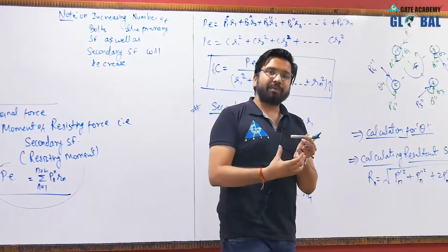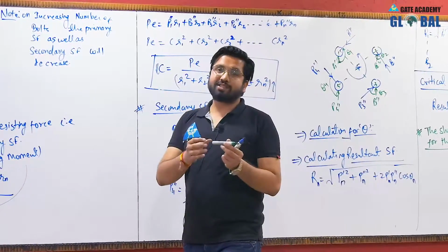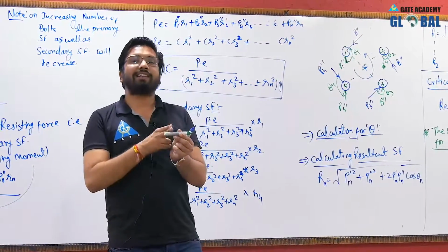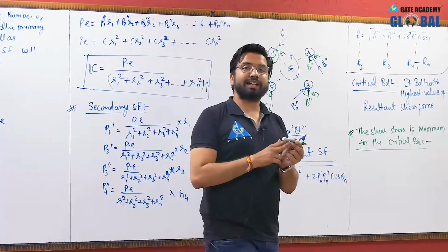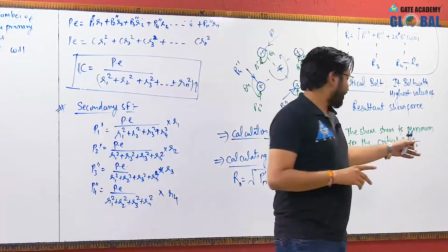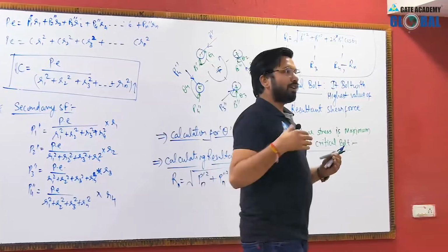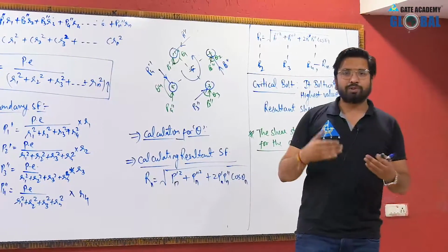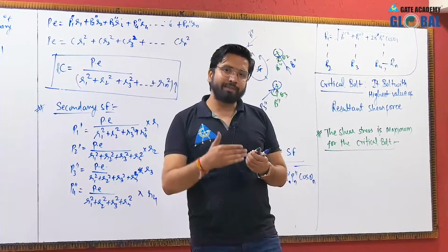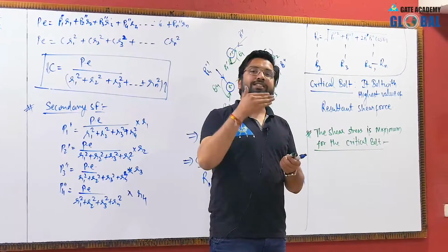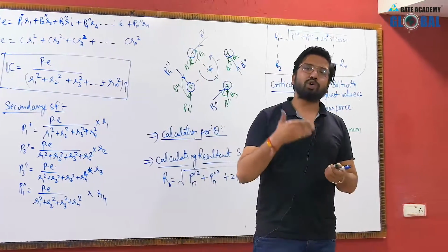So for GATE examination and engineering services examination and different examinations like this, you will always assume that the shear is taking place at the strongest portion, that is the shank portion. So the shank portion will be subjected to shear. So this shear stress will be acting on the shank portion. Although it is very useful to design the bolts or the screw for the minimum area, that is, for minimum area the stress will be acting at the core area, that is the area based on core diameter of the